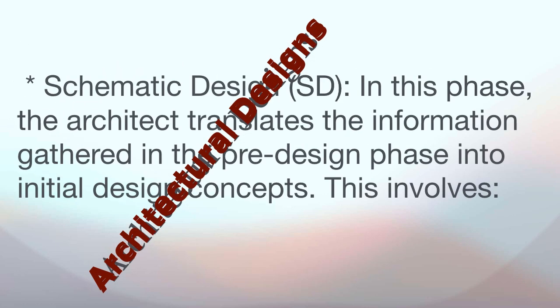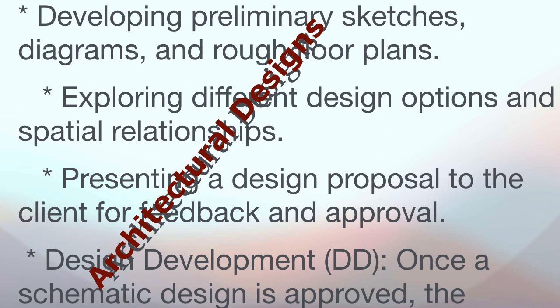Schematic design, SD. In this phase, the architect translates the information gathered in the pre-design phase into initial design concepts. This involves developing preliminary sketches, diagrams, and rough floor plans, exploring different design options and spatial relationships, presenting a design proposal to the client for feedback and approval.